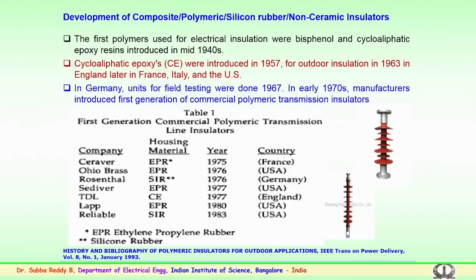So, further we have discussed the manufacturing of the porcelain or ceramic insulator and the glass insulator. Both are electrically and mechanically stable, very good, and have been used for a very long period of time, more than a century-old technology. A lot of changes have happened in both the ceramic and glass insulator pertaining to the voltage level, the creepage distances, and the shapes, which have undergone several changes and are being used.